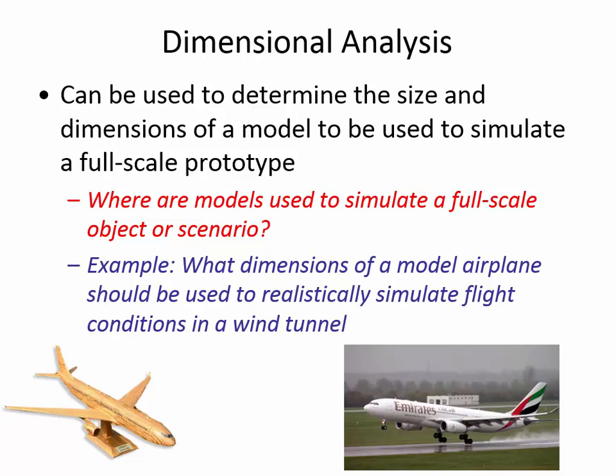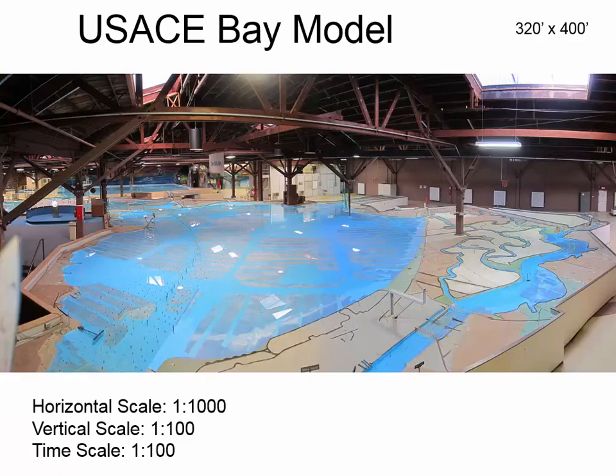But the way that they came up with the idea of whether to use winglets or not is by tests in a wind tunnel where they have some mock-up of a small size airplane made out of clay or wood or whatever they can shape easily. They put it in the wind tunnel and then they measure the drag. They do visualization of the flow. They'll have wind going through there, and they'll maybe add some particles like a very fine dust, and then with a high-speed camera track those dust particles so they can see where the particles are going as an indication of what the flow inside of the wind tunnel is doing. So dimensional analysis is a numerical tool that we use in order to interpret model data.